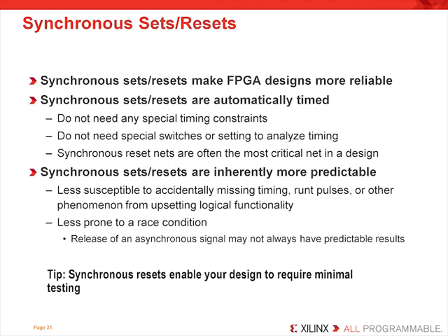Another good reason to use synchronous resets is that they are automatically constrained when users add a period constraint, which is virtually all Xilinx users. What happens is that the period constraint covers the internal delay paths between synchronous elements, and these paths include synchronous sets and resets. For most designers, this makes the FPGA design easier since they have greater assurance that their system's timing report is much more accurate.